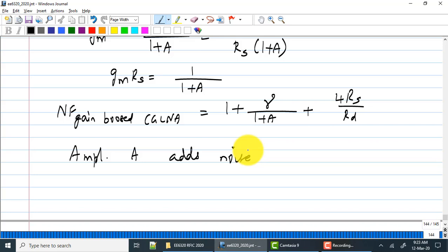A common source amplifier. Since you wanted it to be a low noise circuit, that is the natural choice. But it's only a common source amplifier, it is not an LNA. Remember, the common gate LNA produces 50 ohm input impedance without any inductors. It's a broadband circuit. You do not want to mess that up by having a real input part from the common source from A. So you can choose it to be a common source amplifier.